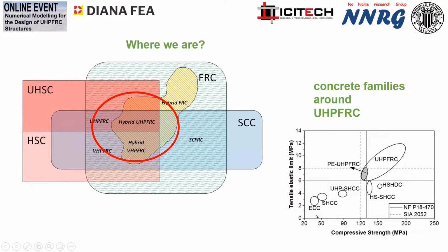You can see that in the market there are other products with a similar concept, thinking in compressive strength or tensile strength, from relatively low mechanical capacity, but always thinking in strain hardening and ductility, up to very high strength concrete close to 200 megapascals and very big flexural tensile elastic limit. We will be in this center. Why in this center? Because it's difficult to obtain a good concept of application in the higher strength capacity elements, and because we want to be structural.